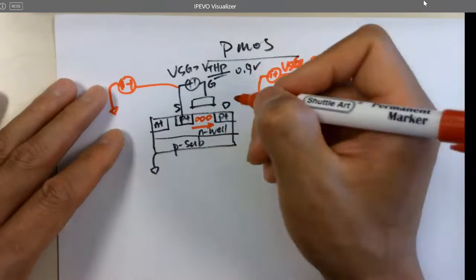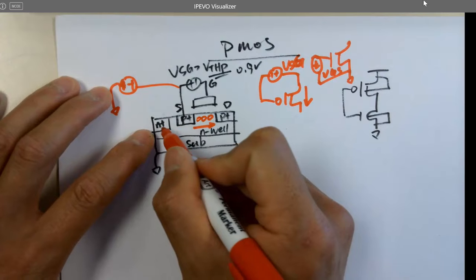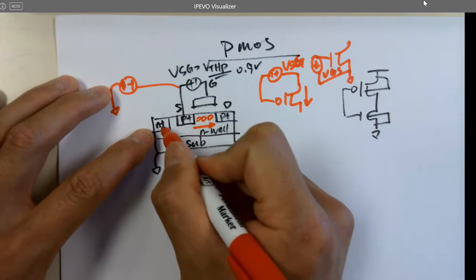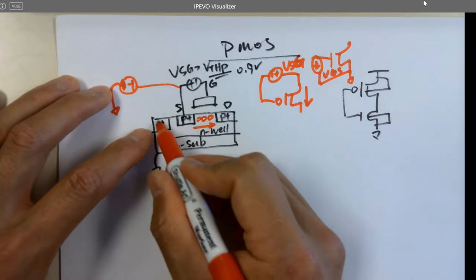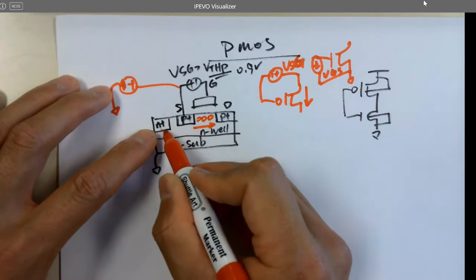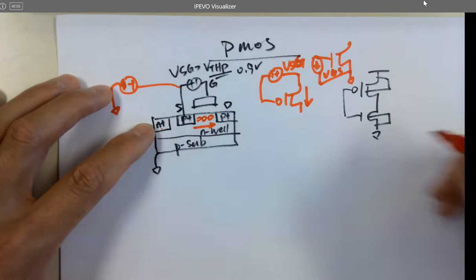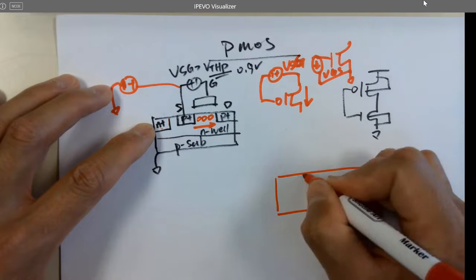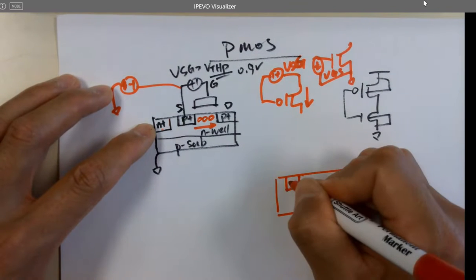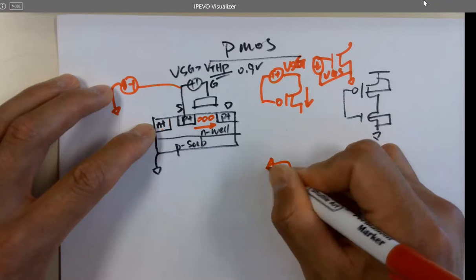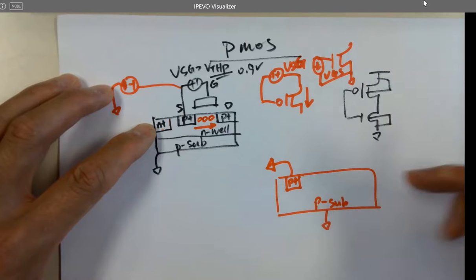Okay, so here, the body of the N well is N plus. Why, if I dope N plus material into the N well, does this become the body? Remember, for NMOS we are not grounding the bottom of the wafer. We dope a P plus here and ground it in order to ground the substrate, because they're both P type, so they're shorted together.